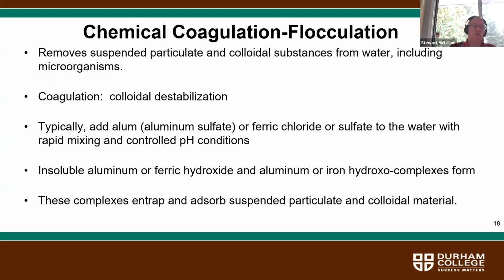In water treatment facilities, they will typically add alum, which is aluminum sulfate, or ferric chloride or sulfate to the water with rapid mixing and controlled pH conditions, and that results in the coagulation of those very small colloidal substances. Insoluble aluminum or ferric hydroxide and aluminum or iron hydroxide complexes form.